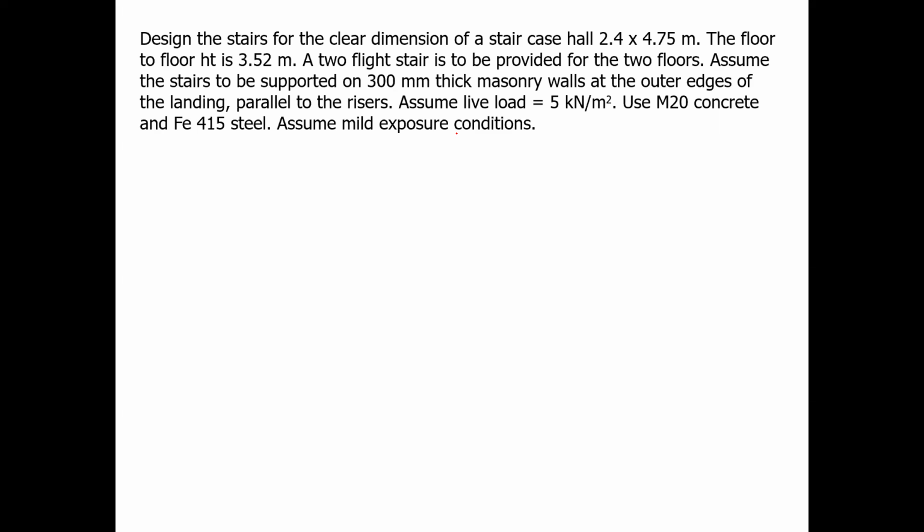Use M20 concrete and Fe 415 steel. And there is a condition given: assume mild exposure condition. So as you considered in design of beam as well as in design of slab, you have to refer to the table for the mild exposure condition, to consider the cover, isn't it?